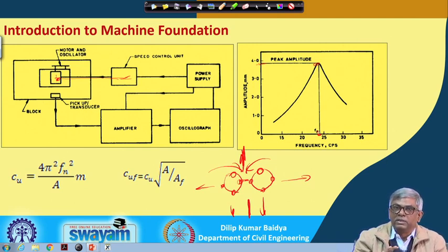Natural frequency and resonance frequency are a little different. If the damping is very high, then the natural frequency and the resonant frequency are slightly different. At resonance frequency the amplitude is a maximum. So, truly speaking this is the resonant frequency, and it will be a little different from the natural frequency, with a damping correction, but if the damping is small then the natural frequency can be approximated as the resonance frequency.